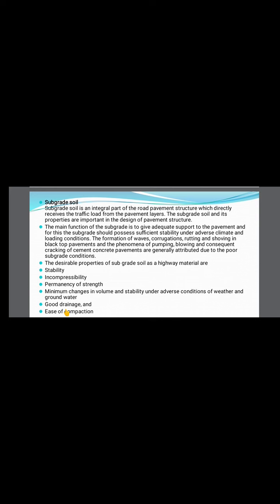In the summer it is different, and in winter it is different. The subgrade soil is very attractive to water. If the water enters into the subgrade, what happens? It will swell, isn't it? So to maintain the stability and adequate strength is very important in subgrade soils.